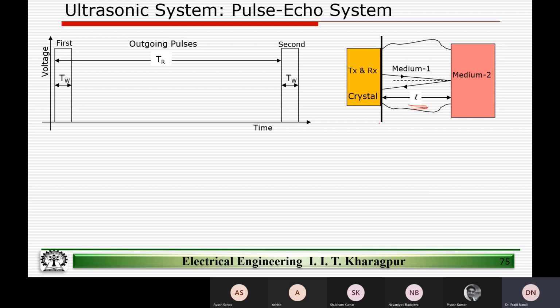If it's, let's say, for the car automated driver assistance system, I know this is going to be air. So I know what the speed of sound will be. And based on the time between these two pulses, and the speed of sound, I can calculate the distance to the object, L. So this is pretty straightforward, no complications. Any questions up to this point?